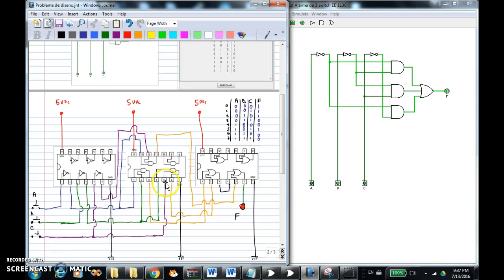So this is B inverting, and pin 5 right here goes directly to where? To C. Alright, this is B inverting with C. Alright, we already have that. The output of the AND goes where? Oh, put it as the second input right here.